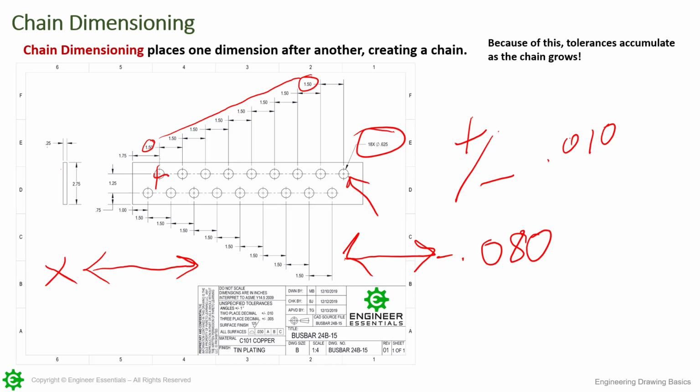Well, really what you're going to be doing is adding it, because you're going to have to go back and add it to the 5/8, depending on where the design is for what this is supposed to clear. So if we're going to leave the 5/8 and that's going to work for this first hole, we would have to come back in and add 160 thousandths in diameter to all of them in order to get them to work, if we were going to leave them as one pattern.